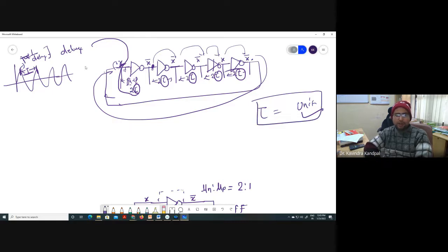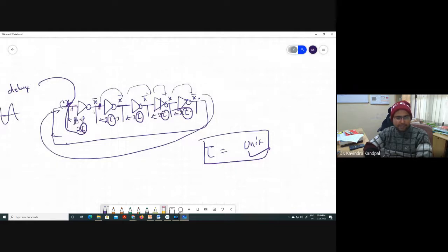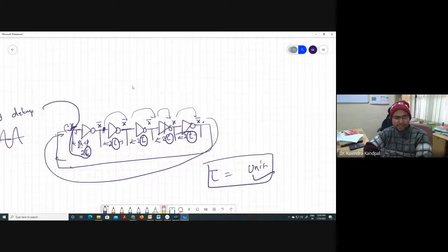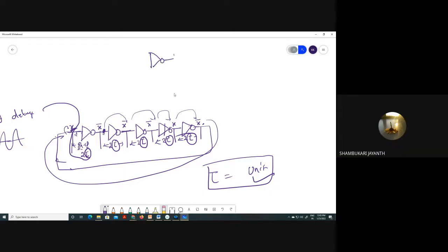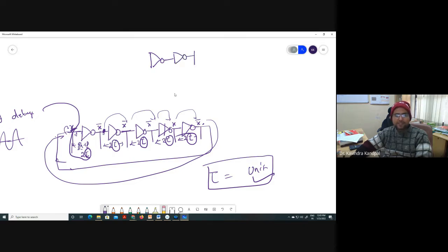Have you made this ring oscillator in your class, like DSD? I mean, discussed a little. Discussed, you have not made it? Take it as an exercise in your LT Spice. Make a ring oscillator with 5 inverters, measure its delay, and compute the value of tau, and compute the tau logical effort. Remember, use the Spice level 3 models which were uploaded yesterday.